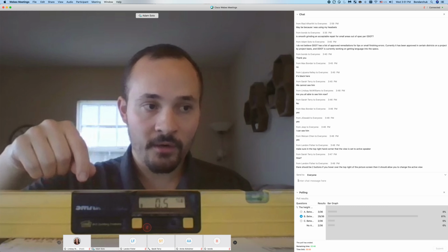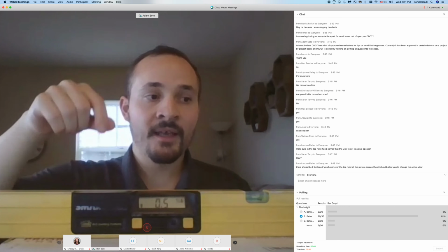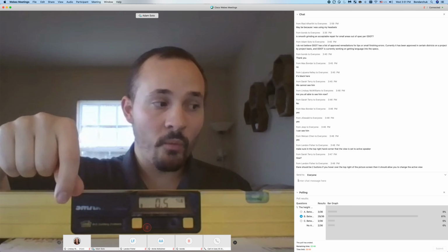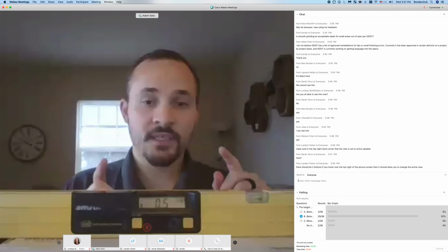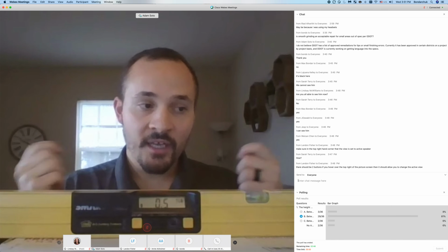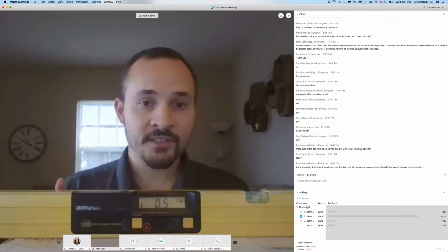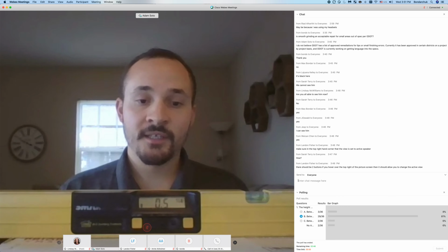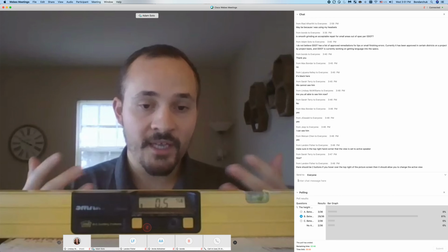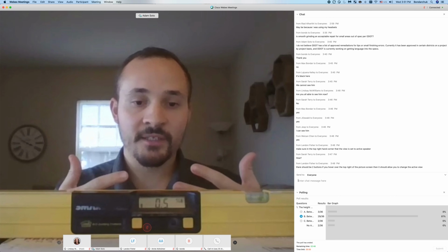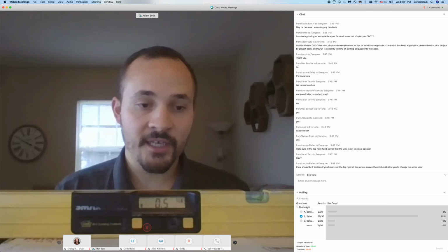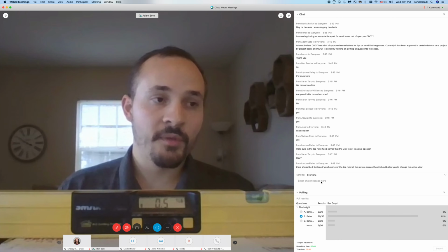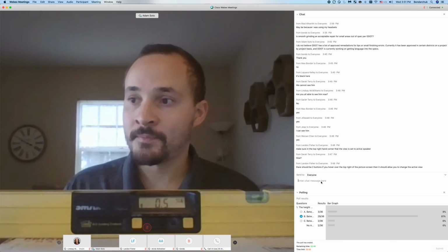And so anytime that we're inspecting something and it's failing at 2.1% or 8.4%, really close, we always want to get the level in that same exact spot and flip it 180 to make sure that it really is. If you flip it 180 and it's reading 8.3 the other direction, then that's when you get everyone together and calibrate the level in front of everyone and find that same exact spot and make sure that it really is failing. So we don't want to be failing ramps that are actually passing.